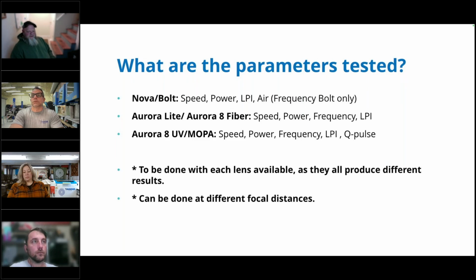That way, as we start diffusing the beam, we get that variation in the material so that we see what that difference is. Especially if you go from, let's say, wood and then you want to engrave a tumbler, you need to make the dot size a little bit bigger by defocusing, but you still need to see what that looks like. So you run a material test.